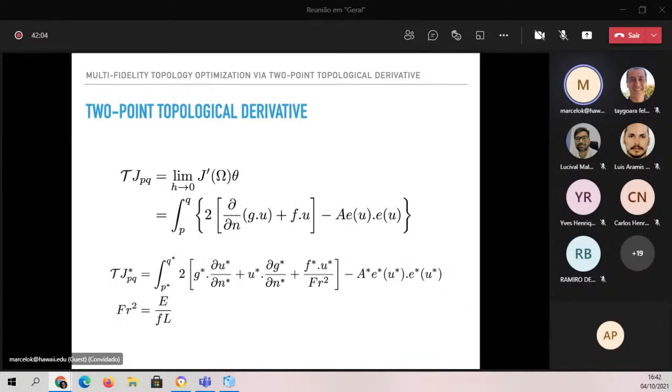The second term will be important only when you have really large variations of the traction due to changes in the shape. For example, in the case where you have a constant traction over the layout, that term is 0. And that will be, in terms of a wing, only really significant when you have, for example, shock wave boundary layer interaction, where minor changes in the shape around that area would create enormous change in the heat transfer and consequently the deformation.